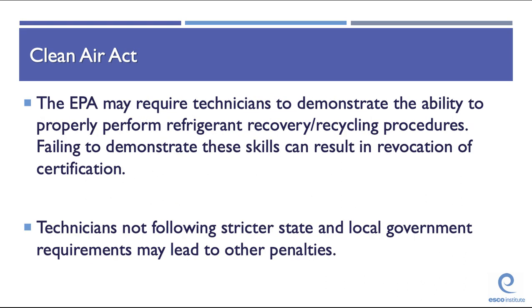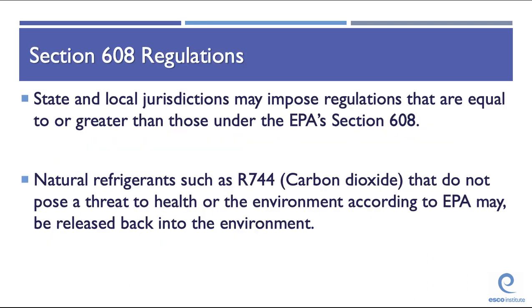The EPA may require technicians to demonstrate the ability to properly perform refrigerant recovery and recycling procedures. Failure to demonstrate these skills can result in revocation of certification. Technicians not following stricter state and local government requirements may lead to other penalties. What this boils down to is EPA sets a minimum standard. Any state or local government may be able to set higher standards as a part of their building codes. State and local jurisdictions may impose regulations that are equal to or greater than those under EPA Section 608.